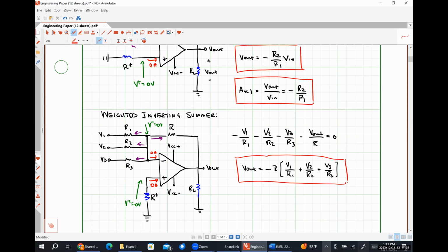So we don't want them higher than RN ever. If they were higher than the internal input resistance, this current would no longer be zero. So these resistors right here typically need to be significantly smaller than the input resistance so that no current branches off and flows here. This load resistance needs to be larger than the internal output resistance, or we'll see that effectively the voltage divider in our practical op amp model causes too large of a voltage drop over the internal output resistance.